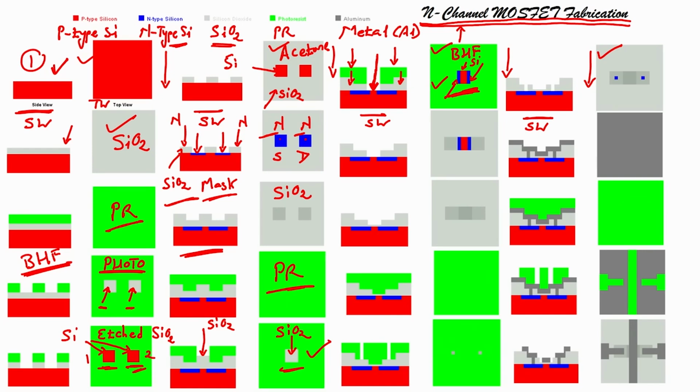So, after this what do we have to do? After this we have to etch the PR, or strip off the PR. Stripping of the PR is by dipping the wafer into acetone, correct. So, we are now dipping the wafer into acetone, and we will get this particular wafer. We have silicon directly exposed here, and a little bit of source and drain areas are also exposed. You can see drain, source and silicon, three things you can see, right.